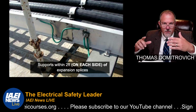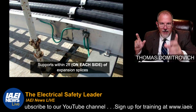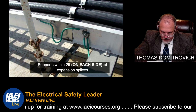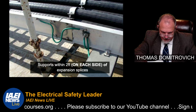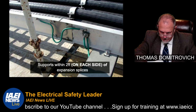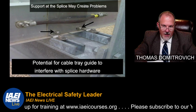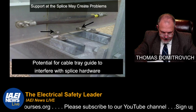Now, see that jumper across that splice plate, or expansion joint? It's a method to ensure the bonding. You'll look at this in the installation, and you'll find a lot of different areas of bonding. Proper bonding. Here's another one. Here's a good one here. Support potential for cable tray guide to interfere with splice hardware. So using the wrong fittings, that's just an example.